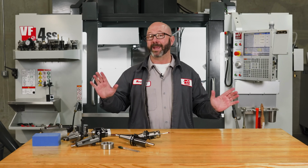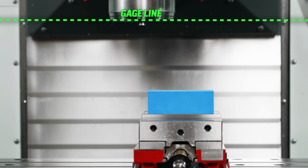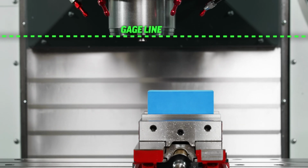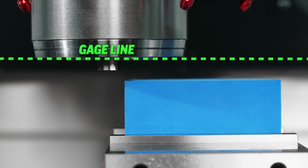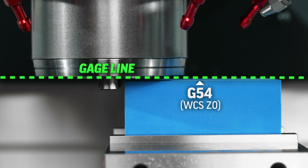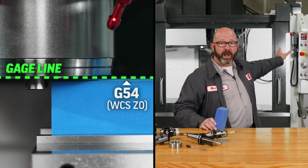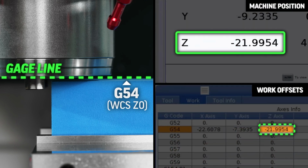Now, I don't want to break anything, so we have swapped out our steel for a chunk of foam, and we're going to jog down our spindle until our spindle gauge line reaches the top of our part, our WCS Z0. And check this out. On the work offset page, we can see that our current machine Z position exactly matches our probed G54 Z work offset.